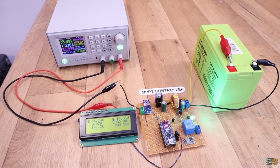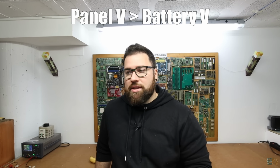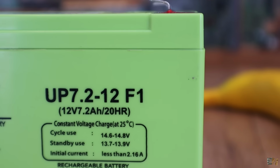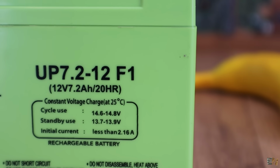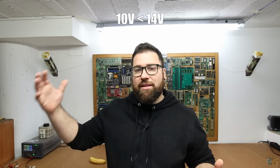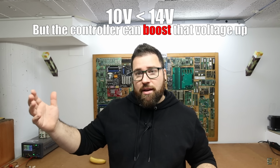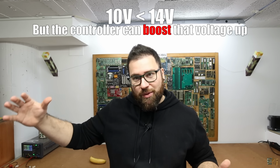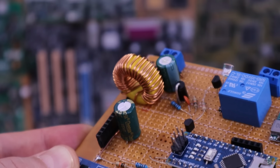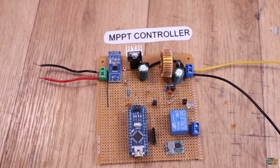Because in order to charge a battery, the voltage of the panel must be higher than the voltage of the battery. So if the battery, for example, has to charge to 14 volts and you only have 10 volts, you will never be able to charge the battery because the voltage of the panel is lower than the voltage of the battery. And by potential difference, the voltage from the battery will try to go backwards to the panel. Usually you have a diode to prevent that, but you need a higher voltage from the panel than the voltage of the battery.